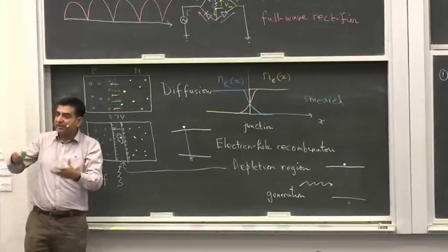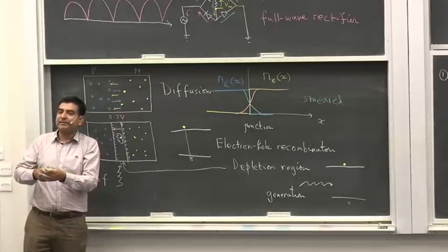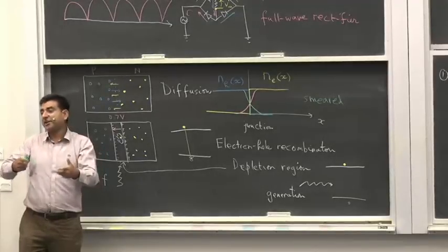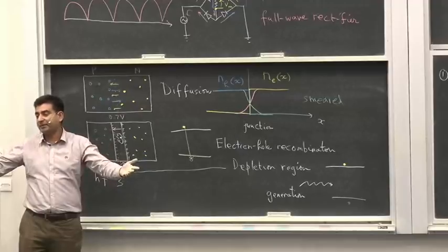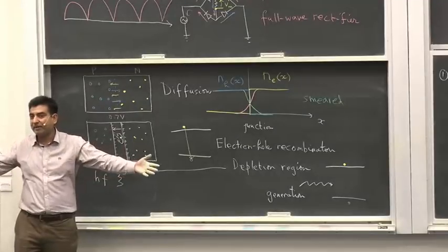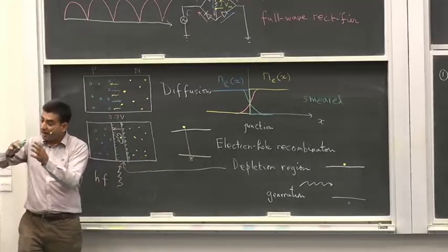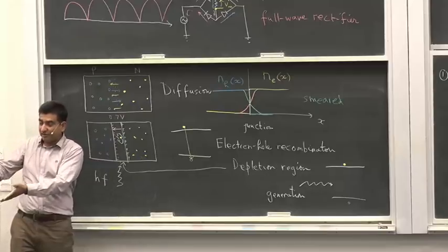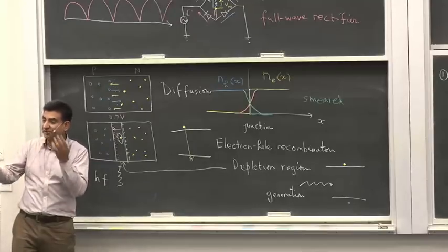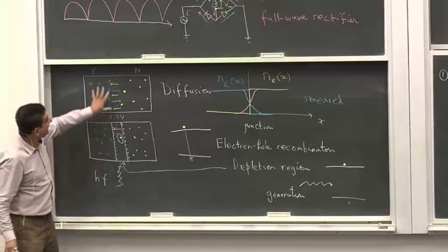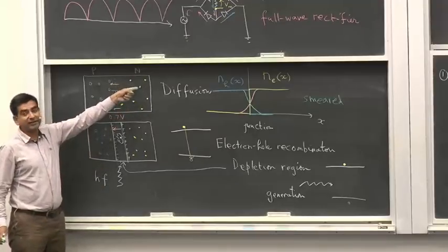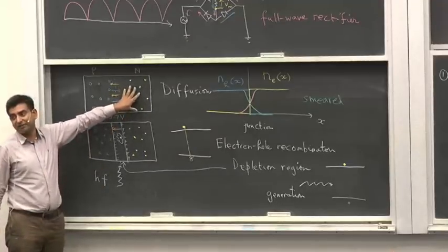And when they come into the crystal structure, into the lattice, there's one extra electron that is not required to bond with the neighboring silicon atom. And that electron becomes a free electron inside the conduction band, but the arsenic, the dopant, is neutral, and the host, the substrate, the matrix is neutral, so everything is neutral. So here everything is neutral. Even though I've drawn an electron, it doesn't mean that there's a negative charge here.